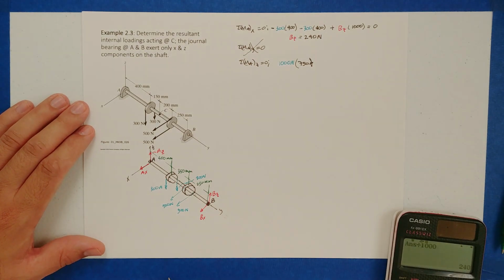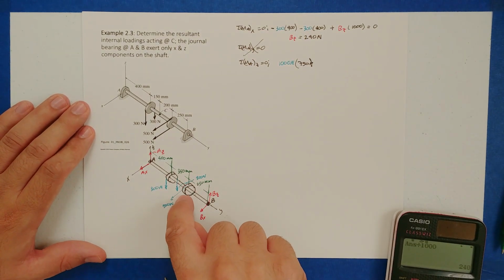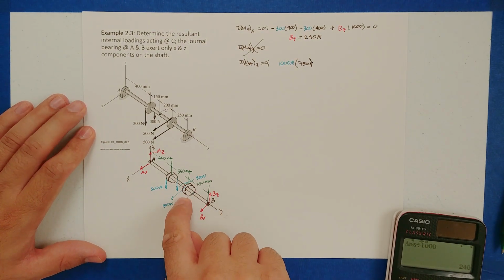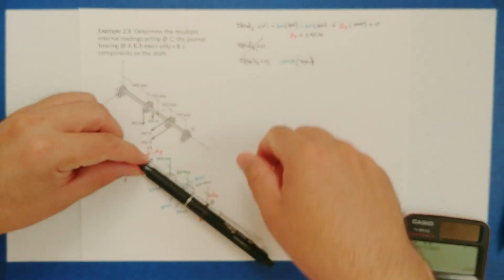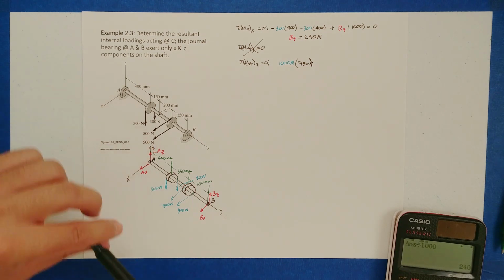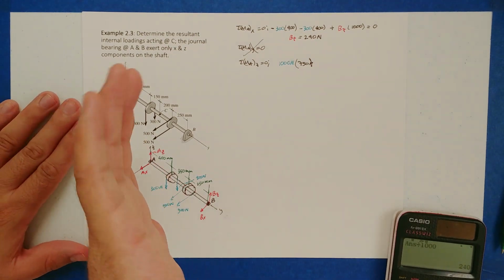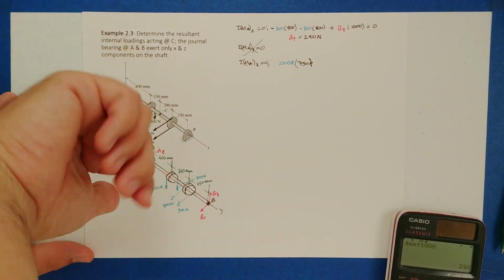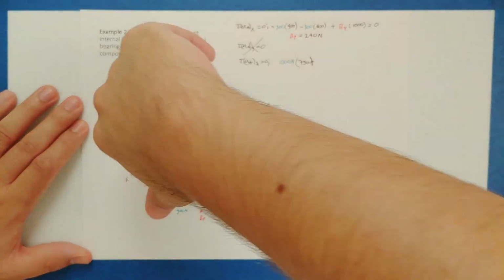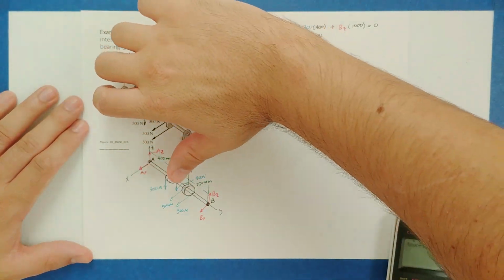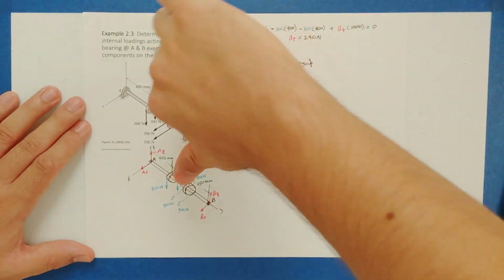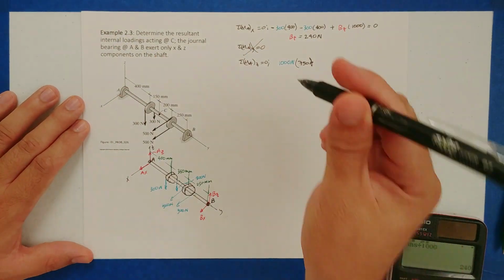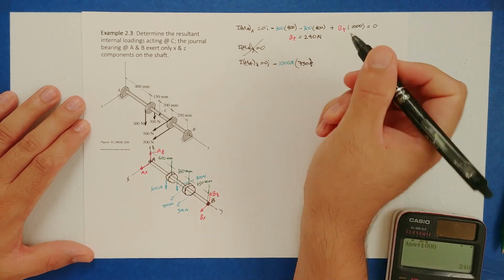The next question is, what is the direction of the moment generated by these two forces, right? Well, since they're pushing this way, they're going to make the shaft rotate like so. If we use the right-hand rule, that rotation is in this direction, right? So imagine here, I hope my arm is not in the way, but it's doing something like this, right? So notice my thumb is pointing down, so that would be a negative moment.